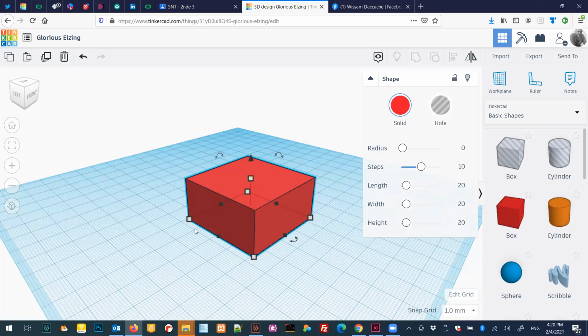Now you have to pay attention, or make students pay attention, to additional tools to manipulate the box, which are this small black triangle, which helps you raise your object from the floor, and you can have this angle of rotation for three different sides.